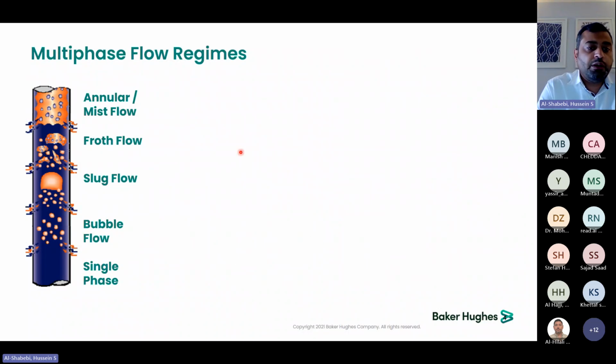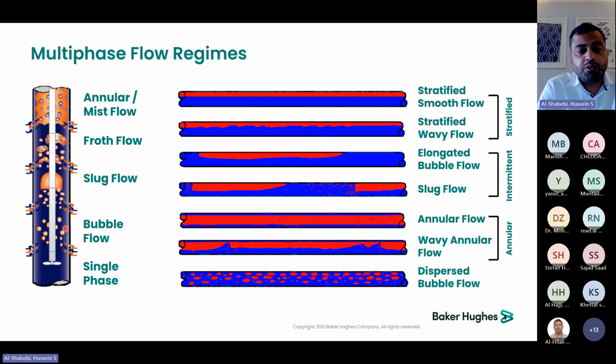So the selection of the production logging tool depends heavily on the flow regime itself. As you can see in this image over here, this is a vertical well. The flow regime in vertical wells is usually homogeneous, either single phase or bubbles, so the distribution of the holdup and the velocity is almost homogeneous. So a single spinner or a single probe for holdup measurements can be applied to achieve the production profile objective. As the well starts to go deviated or very horizontal, the flow will start to segregate.